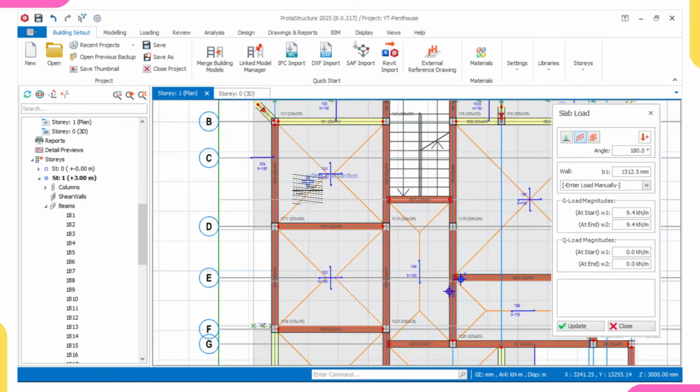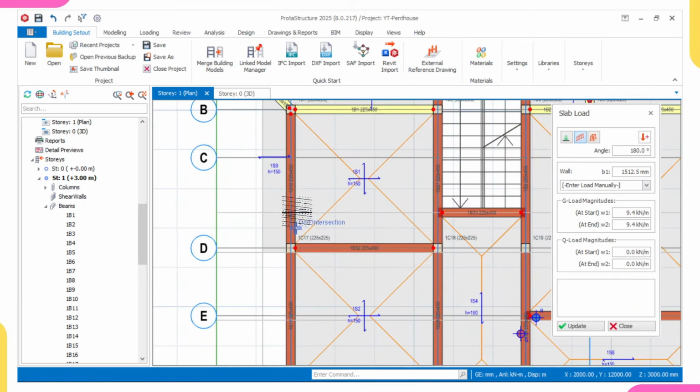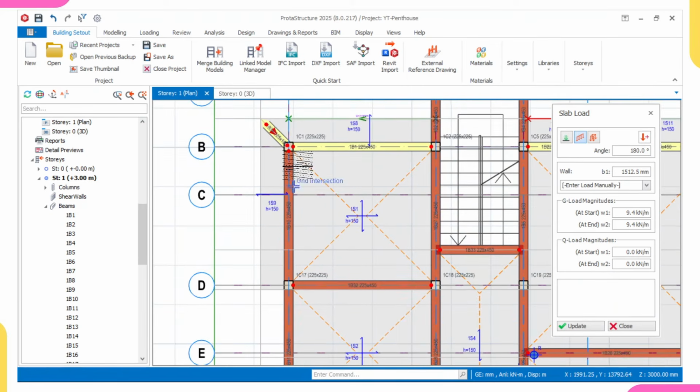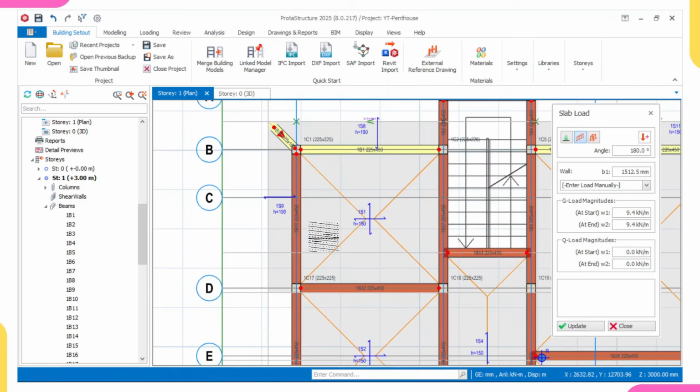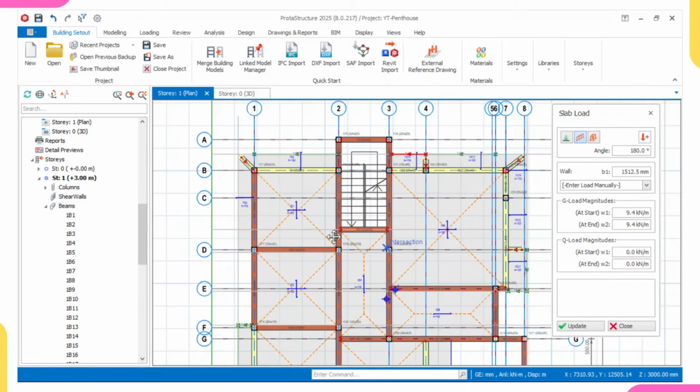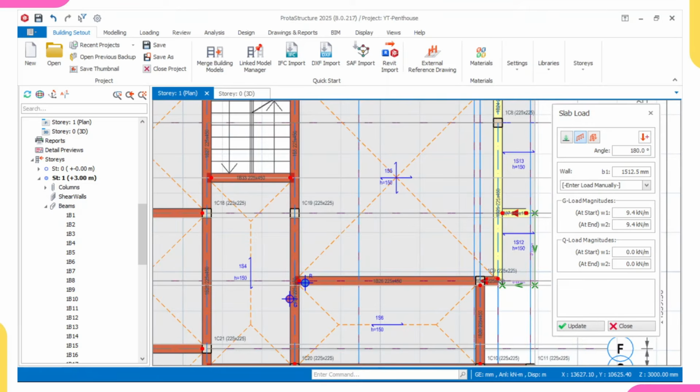The reason why I said let me apply this load on this beam is because before I apply line load on this slab, I have to insert an axis. I can't apply any line load on just a normal slab. I must insert an axis, then apply it on top of that axis. But since the length of this video is already much, I just say let me ignore it and apply it on this. That's why I say you should get the paid course, because in the paid course, I'm not considering the length of the video because I know you paid for it. So I explain everything. In this case, we'll be using line load and it's still 9.4.